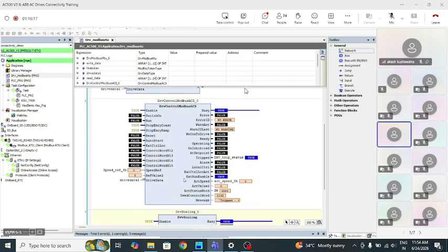Now again in the drive control block, you can see there is an error message which says tripped reset drive. So just go to this reset input and you can reset. You can give a variable and write that variable. So the drive is reset. Here you can see wait for rising edge of switch on input. For troubleshooting purposes, this message is very useful. This is the switch on input. This is a rising edge.